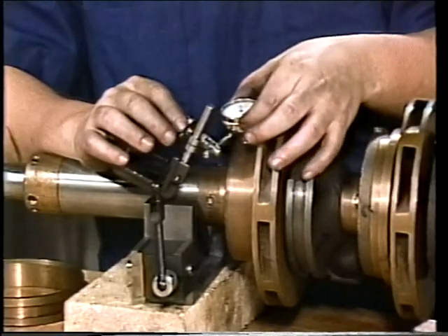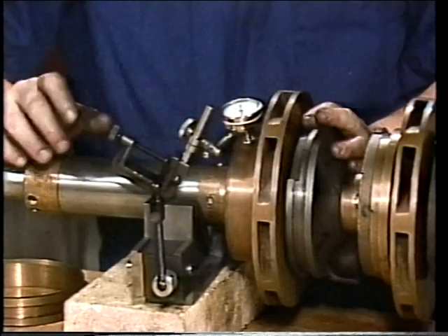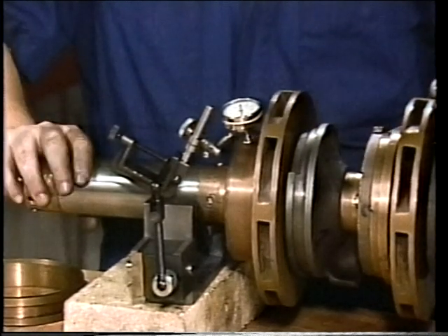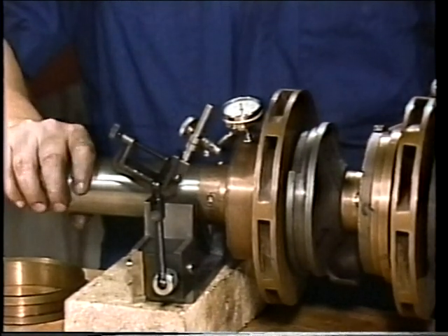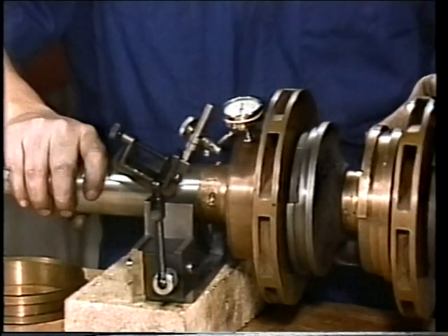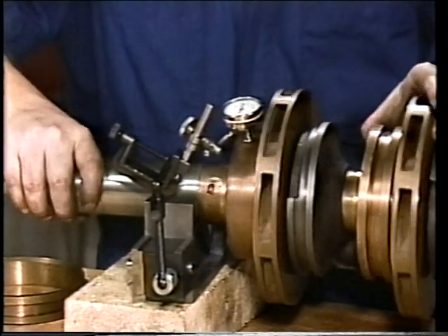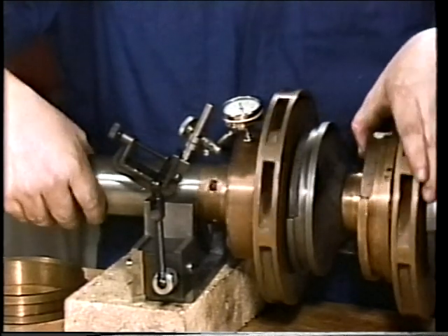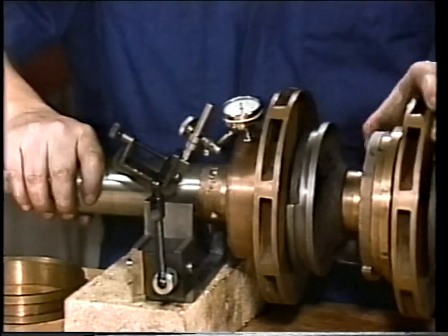For example, vibration could be caused by a shaft that's bent or out of round. The effect of a bent shaft is similar to that of a misaligned shaft. The oblong or eccentric motion of the shaft places additional stress on the bearings and other components. The additional stress causes vibration.